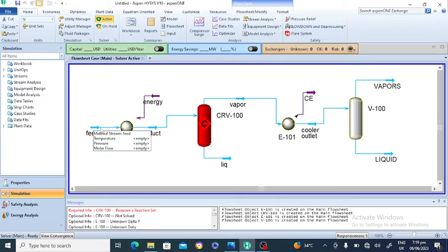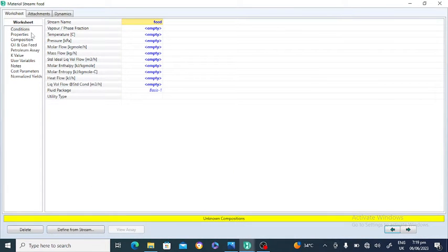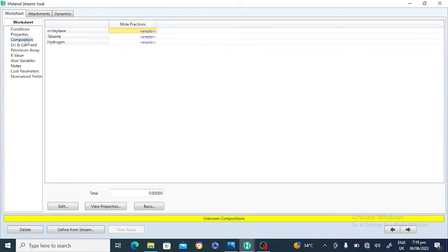The pressure everywhere is 1 atmospheric pressure, and the feed property is given to us. So click on the feed, and here is the feed name, and the temperature of the feed. This feed will go to the heater, and the molar flow rate of the feed, suppose, is 100 kilogram mole per hour. So it is okay, and suppose it is pure n-heptane.